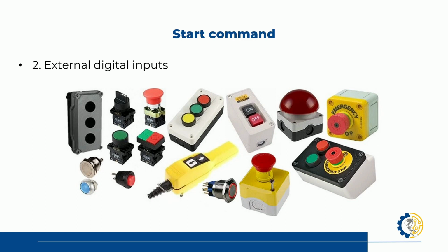We actually have here a different type of button, which is an emergency button. This is pretty important because I've seen many errors with this emergency stop button, and we need to be very careful. I've seen many engineers connect this stop button with a contactor, which cuts the drive voltage only to force it to stop.